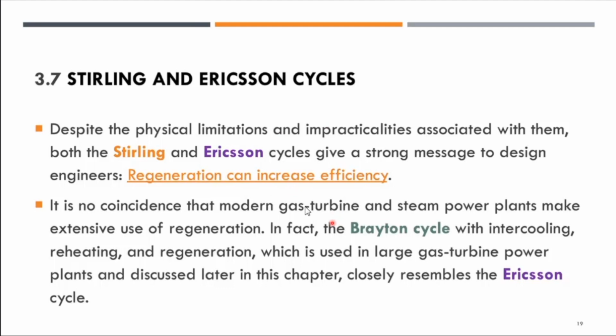It is no coincidence that the modern gas turbine engine and steam power plants make extensive use of regeneration. In fact, the Brayton cycle with intercooling, reheating, and regeneration that we are going to look at later on today, which is used in large gas turbine power plants, closely resembles the Ericsson cycle.